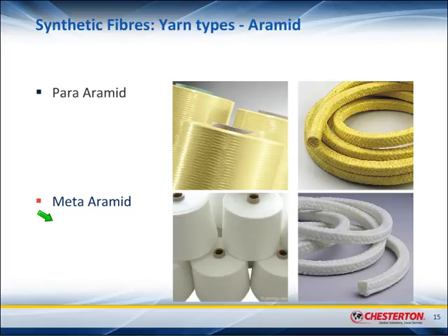The pH range of Kevlar is actually not as wide as the chemical resistance of meta-aramid or Nomex. This is about 3 to 11, and this is about 1 to 13. So this heat resistance and chemical compatibility makes meta-aramid a very nice fiber to use, because meta-aramid is not as strong as para-aramid, but it still has pretty high tensile strength.